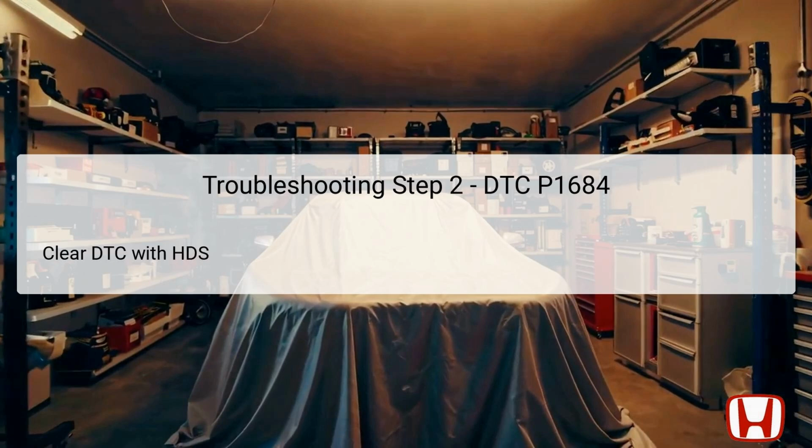After turning the ignition switch to the ON position, the next crucial step is to clear the Diagnostic Trouble Code (DTC) using the Honda Diagnostic System (HDS) tool. HDS is an advanced diagnostic tool specifically designed for Honda vehicles, allowing technicians to diagnose and resolve issues accurately. Clearing the DTC removes it from the trouble code memory, enabling the system to refresh and reevaluate any current conditions.